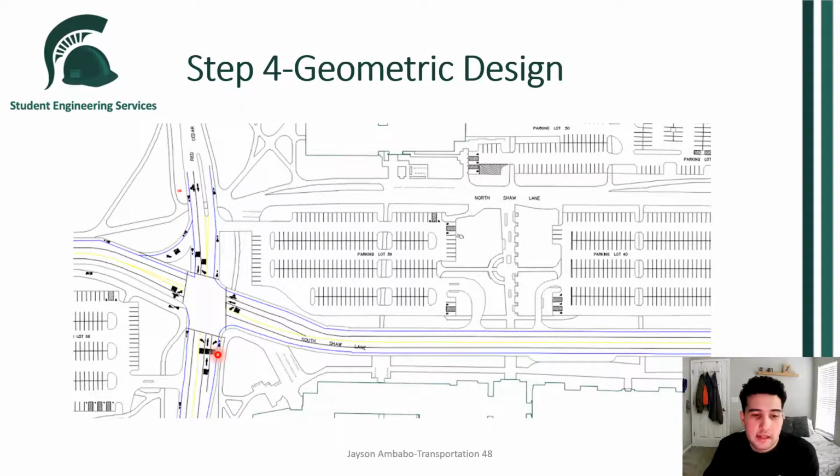A right turn lane was added on North Red Cedar Road. A widened right turn going southbound was also added, and the lane distributions were changed to account for the lack of the signal that was formerly here.